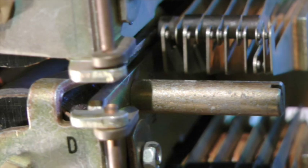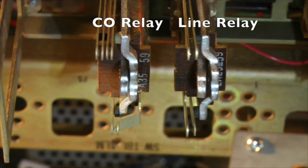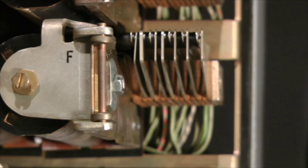The operated D relay performs a number of tasks. The D relay closes a direct path between the grounded sleeve lead from the first selector and the sleeve lead to the CO relay in the line circuit. This path keeps the CO relay operated for the duration of the call. The D relay closes a path between the grounded sleeve lead from the first selector and the secondary winding of the F relay. This path keeps the F relay held operated for the duration of the call.